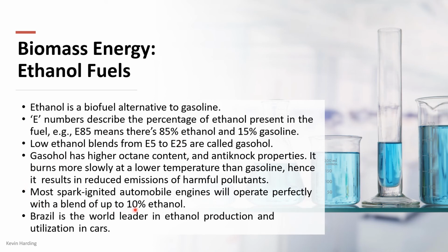Anything from 0 to 10% ethanol, so this is at the bottom here, is normally fine to run in any engine. So ethanol has a similar makeup to the petrol that you put in your car. So if you've only got 10% ethanol, it's not going to affect your car too much, and it should operate. It should. Please don't do it if you find it without checking with manufacturers. It should operate perfectly fine. Anything higher, there might be some alterations that are needed. So this is in petrol tanks.